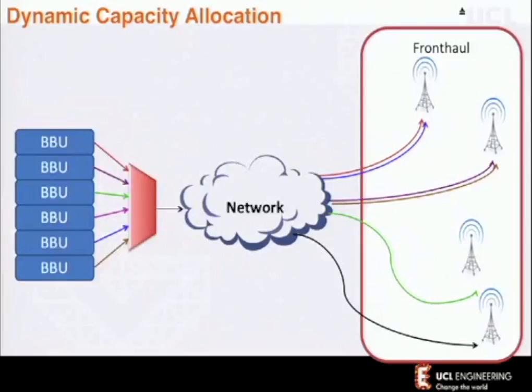I may need quite wideband antennas and amplifiers, and that's another engineering challenge. But now I just rearrange my network, and I view my baseband resources not as something that I design when I build my network. I view them as a virtual pool that I can configure my network with based on the movement of my traffic.